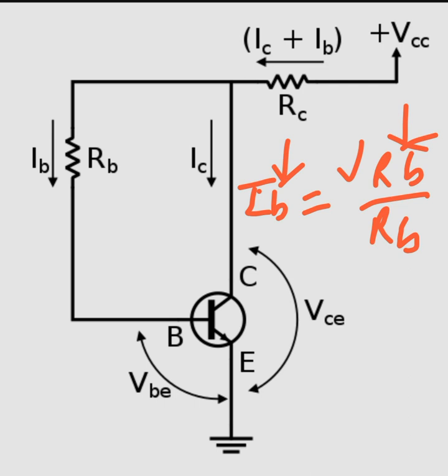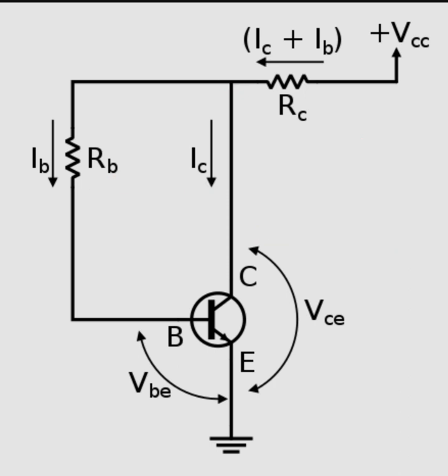So due to the rise in temperature, the collector current rises and the base current will also tend to rise, but due to connecting the resistor RB from this junction to the base, we see that IB is coming down. So that's the effect of negative feedback.